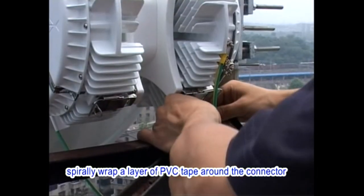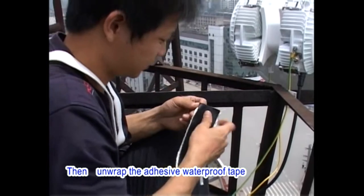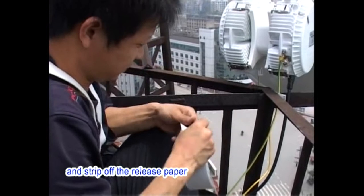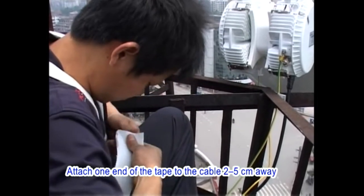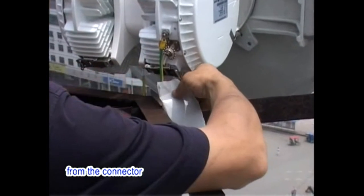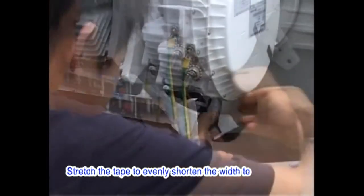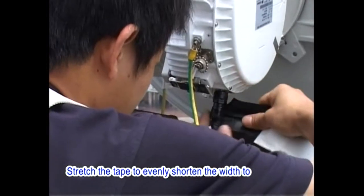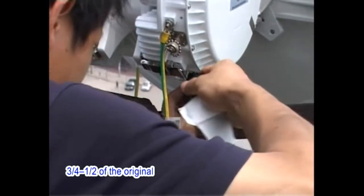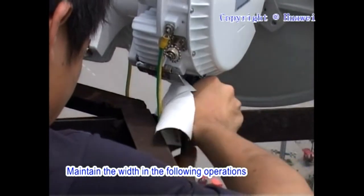First, spirally wrap a layer of PVC tape around the connector. Then, unwrap the adhesive waterproof tape and strip off the release paper. Attach one end of the tape to the cable 2 to 5 cm away from the connector. Ensure that the adhesive layer is facing inwards. Stretch the tape to evenly shorten the width to 3/4 to half of the original. Maintain the width in the following operations.